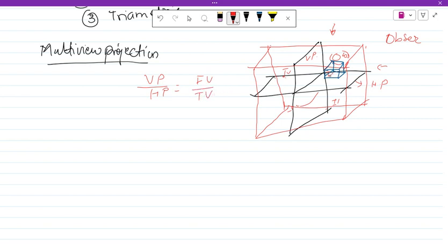For the left side view, I need to see it from here, and this point of view will imprint this visible outline in this plane. So if I fold it here, the vertical plane, here will be our plane 1, and this outer plane will fold here, plane 2. In plane 1 we will look at the left side view, and in plane 2 we have to look from here, and this will be the right side view.